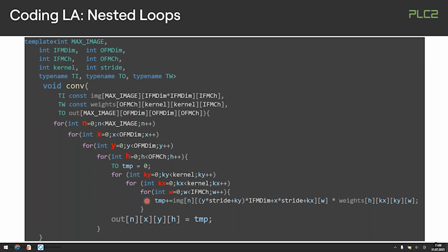So this takes a lot of cycles, but actually this guy is not doing too many different things at a time. And this is where you can do it with the CPUs, but you're not quite efficient. What would happen in hardware, if you would be placing this code in a certain way into HDL code, you would replicate this compute expression in parallel. And you would then simply get the same result. Instead of waiting for n cycles for this loop to be traversed, you would get the same result within one cycle. And the same approach is there within the vector processors, depending on the actual instruction level that you have. So just keep this kind of model in mind.